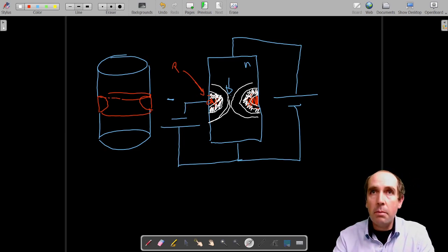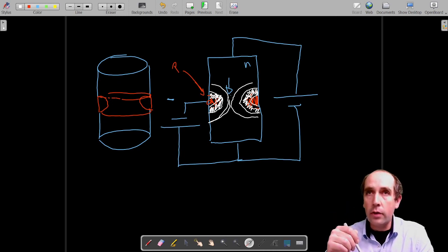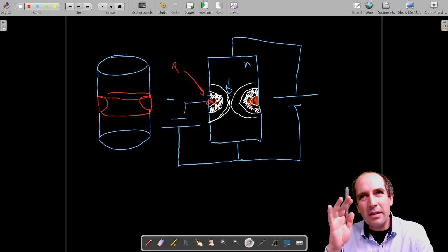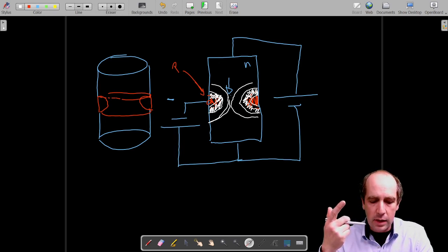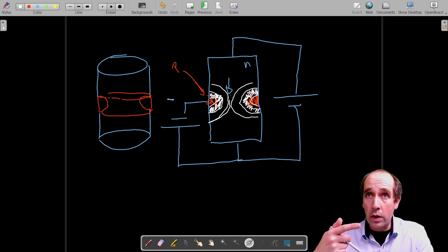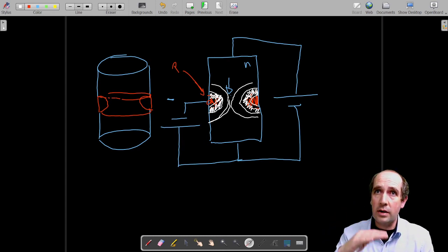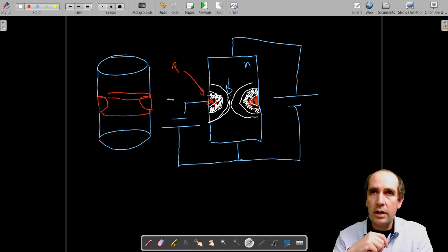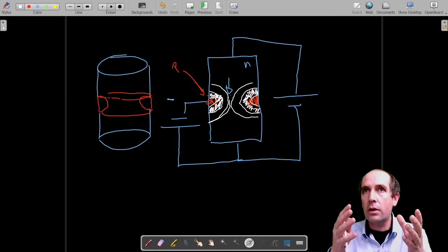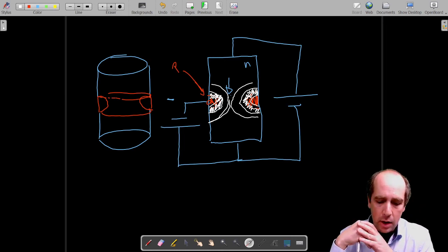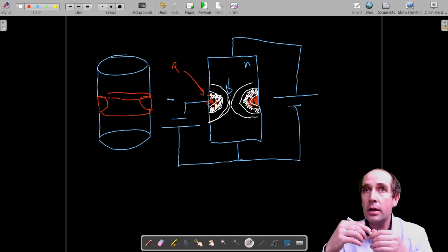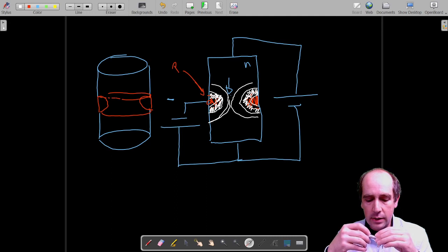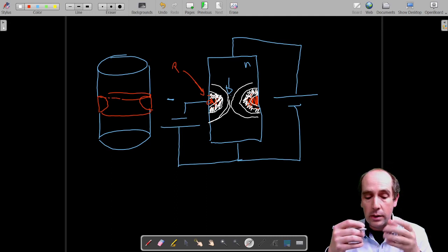We can control how much current flows through the other two terminals. So this is in a sense similar to what we saw. Now the logic is a little bit different. Now the transistor is normally on, and you can start lowering its conductivity until you completely strangulate it and turn it completely off. However, this type of transistor is also very useful. It's called a junction field effect transistor, and it has some differences as well.